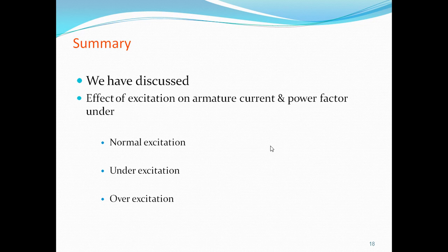Let us consider a synchronous motor with constant load, where at a particular load EB is equal to V and the current I lags the supply voltage by a small angle phi. The internal angle theta is constant. Why? Because it depends on the circuit parameters, that is, theta is equal to tan inverse of Xs by RA.